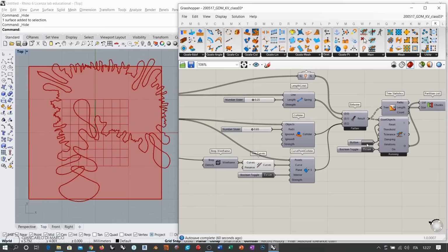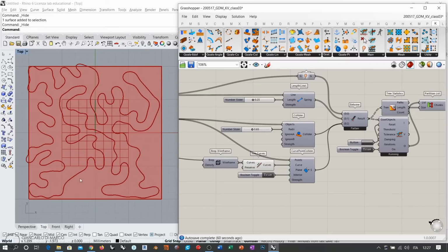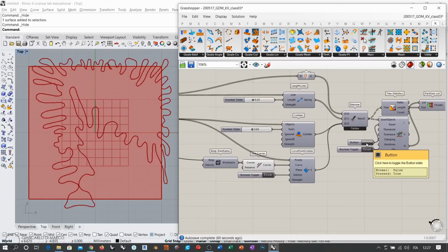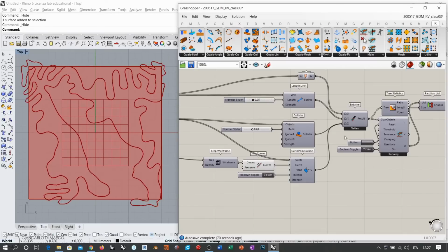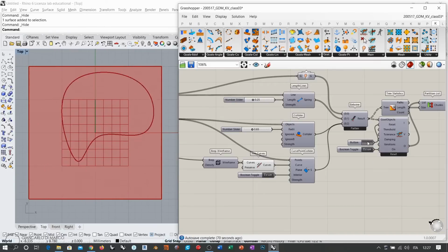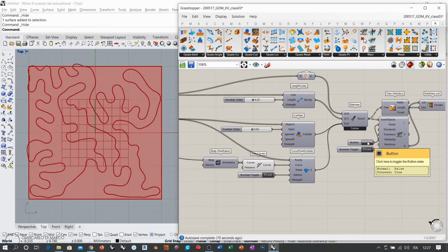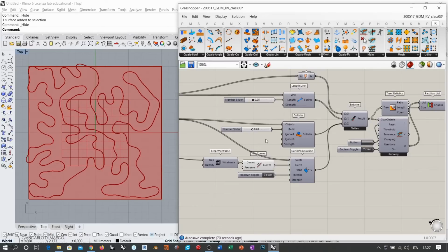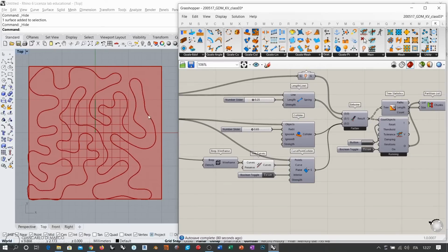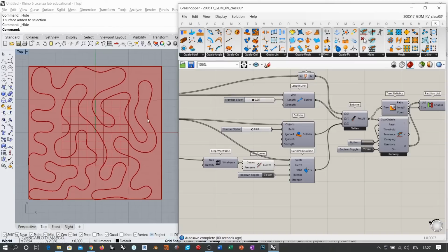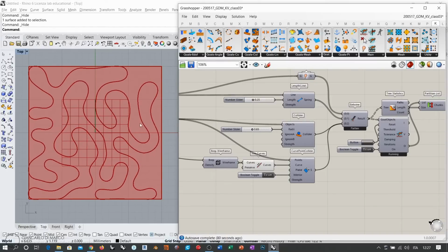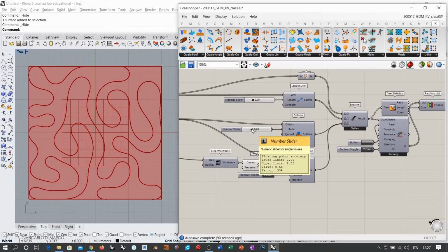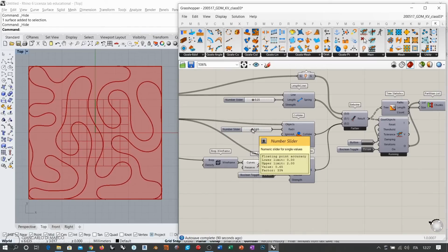And sometimes you might detect that in some areas, for example, here at the bottom, the curve self-intersects for a while, and also here in the top left corner, there is a small self-intersection, but then the curve manages to smoothen its path. Now, this is totally random, so I wouldn't rely on the fact that the curve will take a proper configuration towards the end of the simulation. So I do prefer to control the initial part in order to avoid self-intersection.